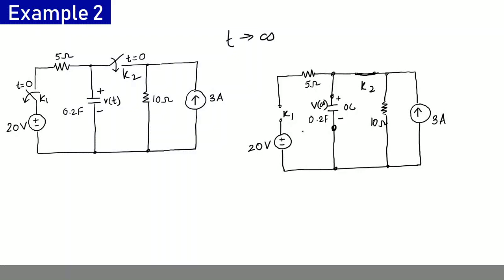Right, so again let us analyze this circuit. This current, 3 amperes, comes from the current source. A part of it should go here. Now, when this current gets divided, there is no path to flow here, so this current will be 0. And because this capacitor is now open circuited, it cannot go here also. So what happens is no current flows in this branch. So whole of the 3 amperes flows through this 10 ohm branch.